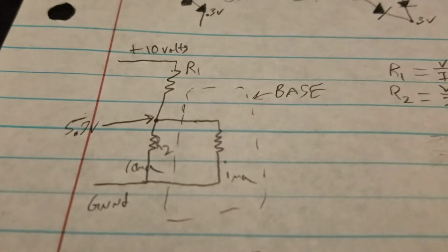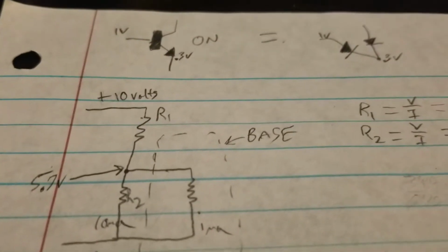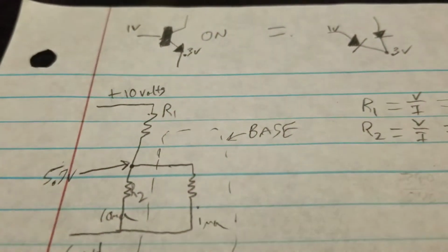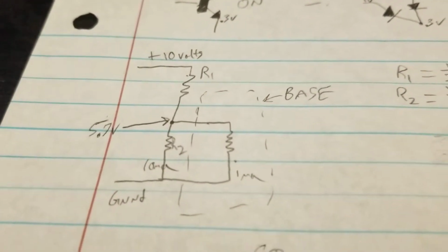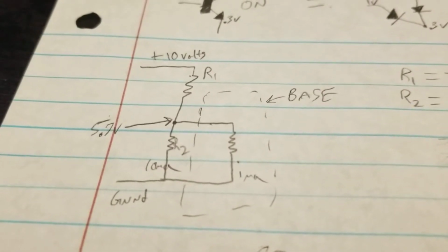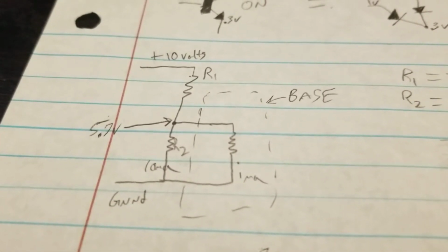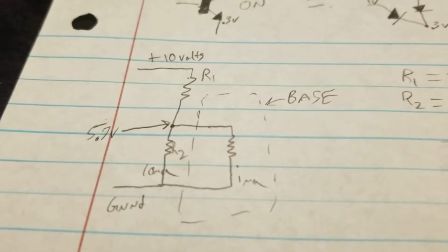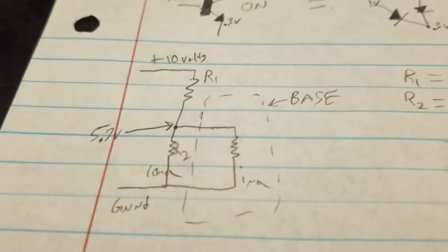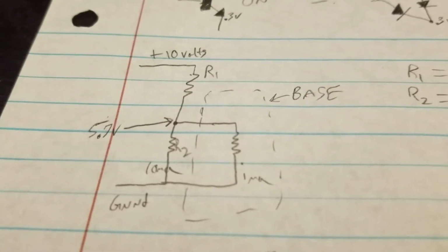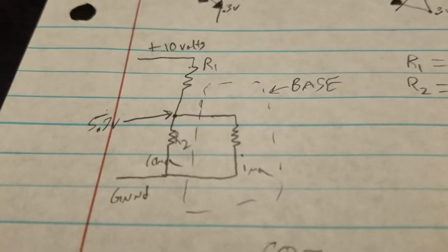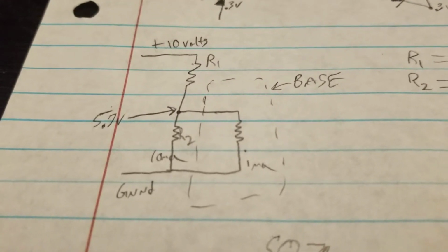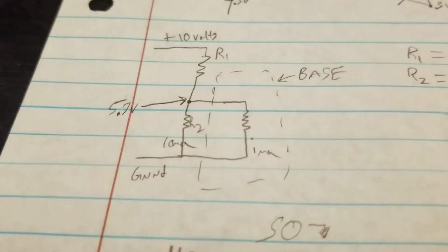Now, why did I choose 5.7? Well, you've got to remember, let's say we want 5 volts on this point here, a smooth 5 volts, 5 volts even, for whatever reason our circuitry needs 5 volts regulated. You have to account for the diode junction voltage drop there. So 5.7. Anyway, you design that, and I'm assuming a base current of 1 milliamp here, and I'm running 10 milliamps through the other resistor and 11 through the divider, so that way it's pretty stiff and